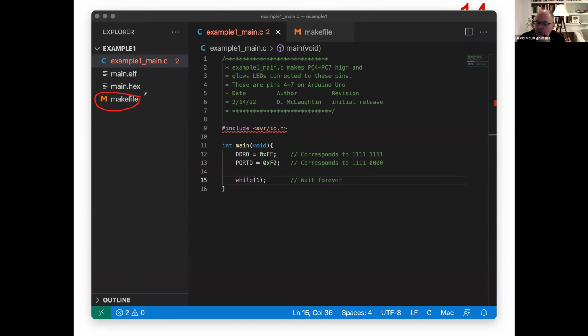There is an analog to digital converter, and port C does double duty. The pins on port C can be used for GPIO like we're doing here, or as analog input. We're going to get to that in a couple weeks. You can think about the analog input as one peripheral, and the GPIO as another peripheral. The way we're going to attack this is to look at all of the different peripherals in turn: GPIO, analog to digital converter, the UART, the timers, the interrupts. As time goes by, we're going to learn about all the different peripherals.